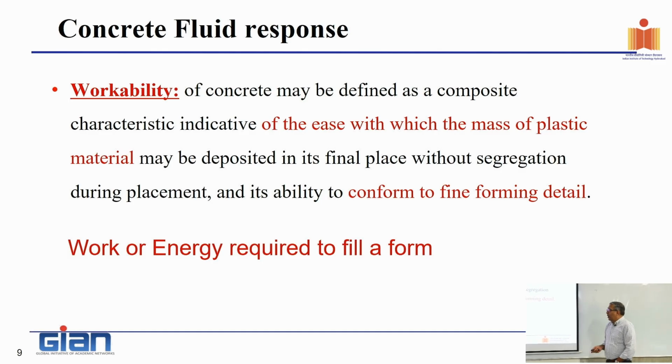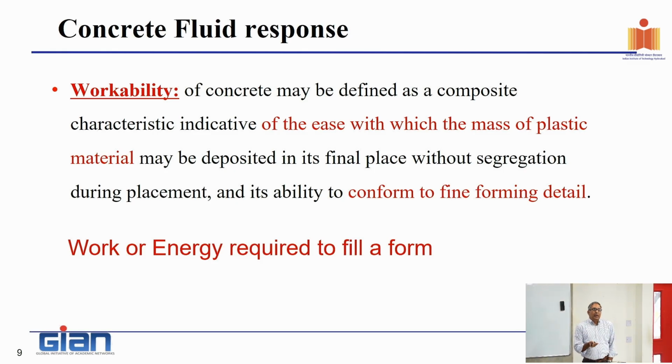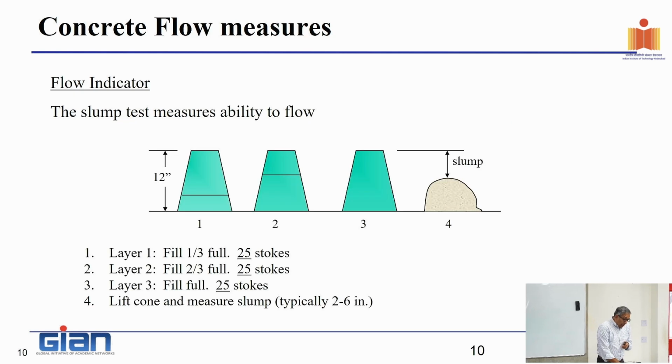Okay. Now, if we were to look at it alternatively, what would be the alternative description of it? What we're looking at is the work or the energy that would be required to fill a form. How much energy do I have to put into this material to get it to conform, how much energy do I have to put into this concrete to make it conform with my requirement? And conformity with my requirement is the entire form should be filled up thoroughly, completely, without any air gaps, right?